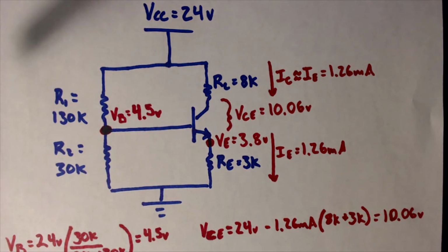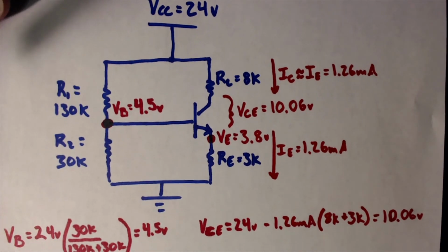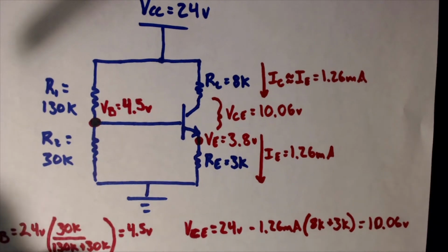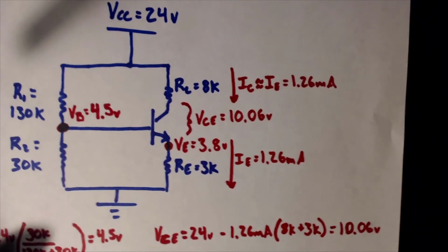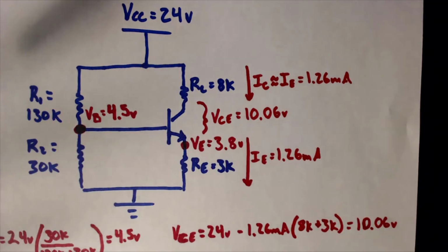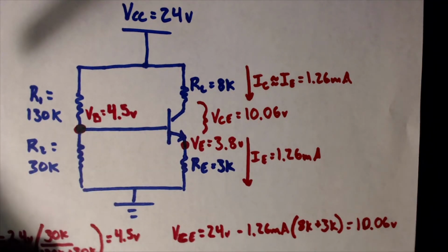So when we're constructing amplifiers using transistors, we have to live with that Q point being somewhere in the center. And that requires us having a voltage that's higher than 0 volts.